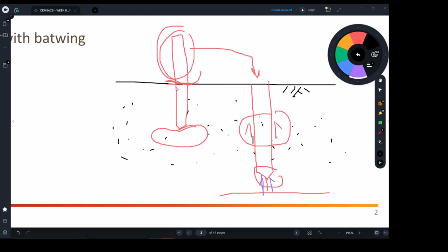So the question for you is saw cut. One thing I want to bring to your attention, there are two types of driven piles. One of them has a pointed or sharp end, and there are also types with a flat end like that. They use the flat end in case there is a second section to hammer on top of an existing one, right? There are some locking details.